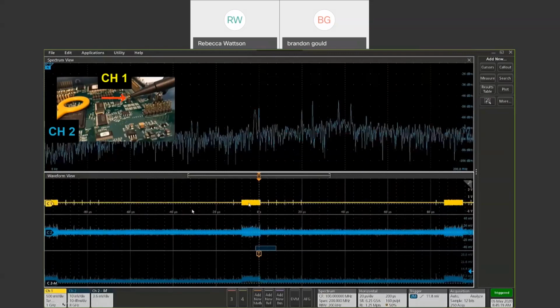So I was able to then kind of trace the circuitry back and see where I was getting leakage from this signal into the pins that were feeding into this FPGA, and be able to determine that the board layout here with this signal was causing that noise to leak in and emit and cause us to fail some of our compliance testing. I was able to correlate my analog signal on this pin with my RF signal here from the near field probe.